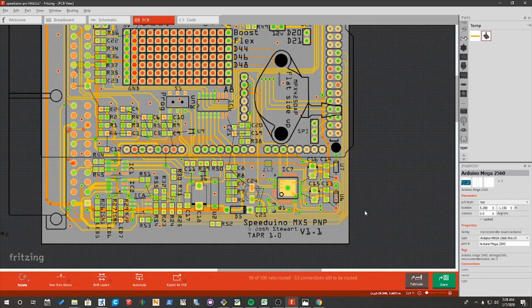So let's go ahead and find pin 29 on our integrated circuit. And when we do find pin 29, what we'll actually find is that it doesn't go anywhere. It doesn't actually have any wires leading to it. So at that point, I was kind of stumped and a little confused. If the thing that's supposed to be creating 5 volts, powering our Arduino, doesn't even have any wires to it, what's actually supplying the 5 volts? So then, if we go back to our data sheet for our integrated circuit and see where exactly 5 volts might be coming from, we can figure it out.